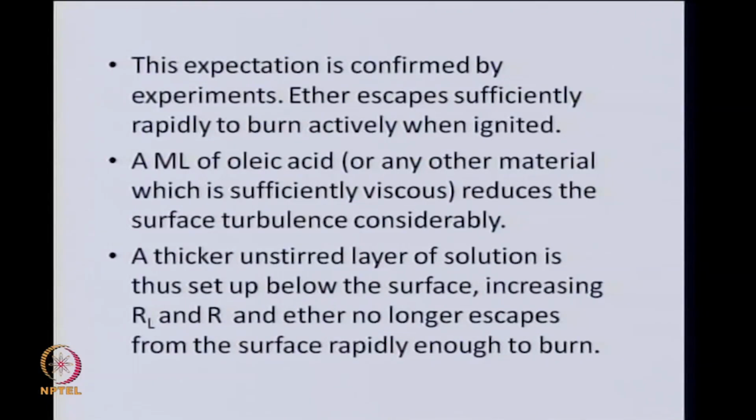So, surface instability can be a reason for observed reduction in the liquid phase resistance, and this is especially important because Ri and Rg are likely to be small here. So, any decrease in the liquid phase resistance will manifest itself into observable rate of transfer, and that is what